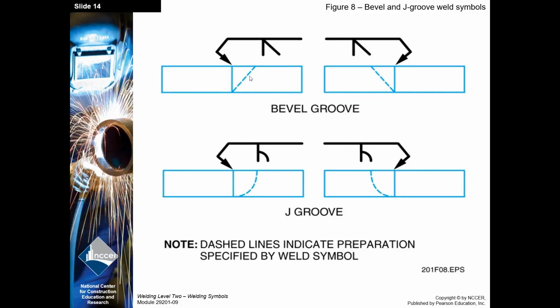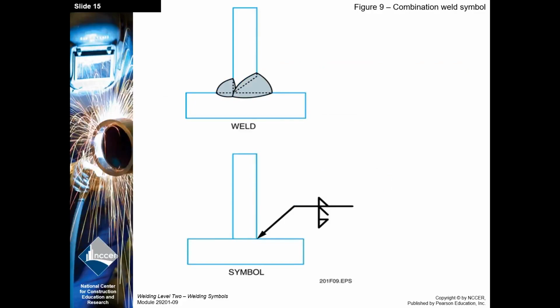All right, and there is a question on one of your quizzes coming up that is like this. It's pretty tricky. They're going to put that symbol on the top maybe. So not only is it kinked, so you got to think, yeah, this side, but if it's on the top, that means other. So the dots have to reference from the bottom to make that appropriate. So watch for that. Attention to detail, right? That's your trade. You're a welder.